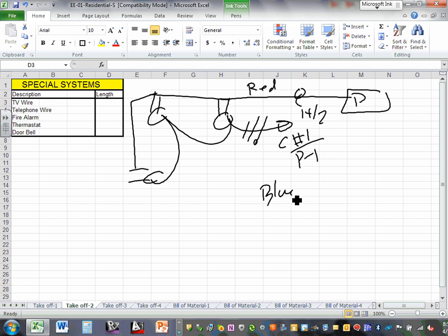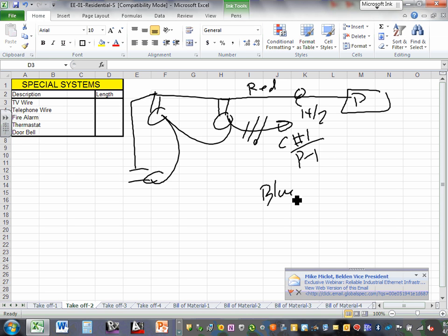I would like you guys to redraw things. I would not accept it unless it's redrawn in right angles, please. So if it's going from a receptacle to a panel, then you just go straight, from a receptacle directly to a panel. Going from here, you're going 9 feet over. How much? I don't know, you measure that, and then down 6 feet. Done. All the way up every time.